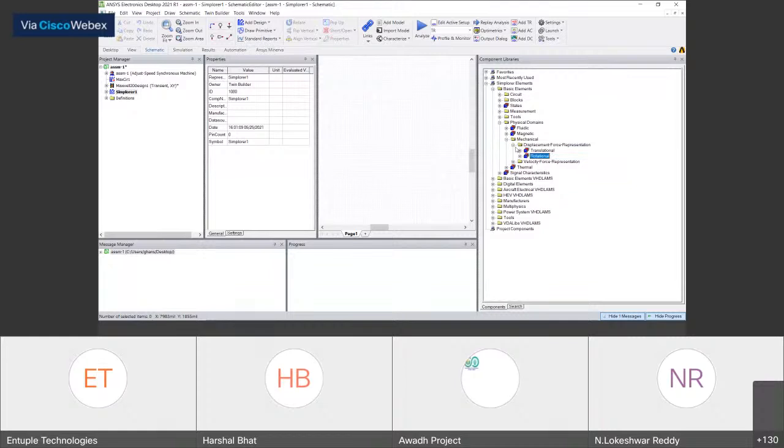So these blocks are generally used to, let us say, give load on a solenoid coil or load on a motor or anything like that. There are also thermal solvers, thermal blocks. And for signal characteristics, you have probes like FFT probe, power probe, which will help you in extracting quantities out of your signals.